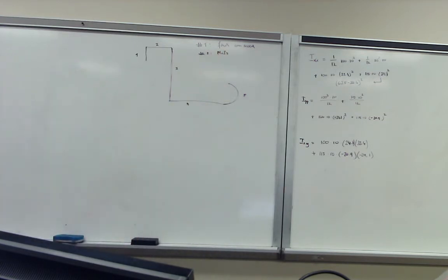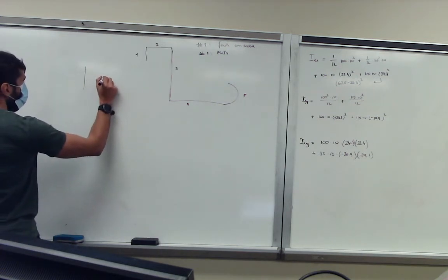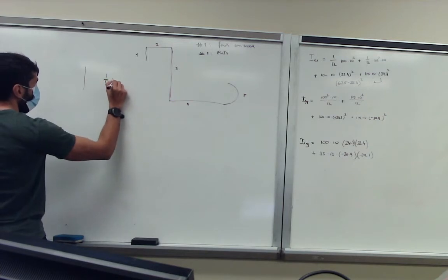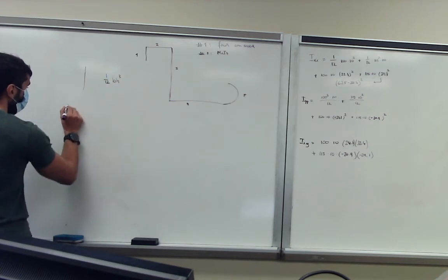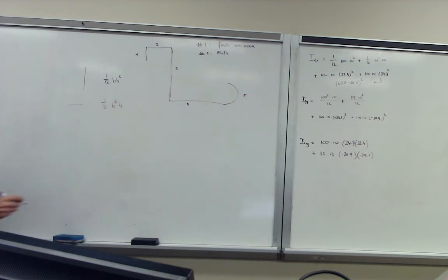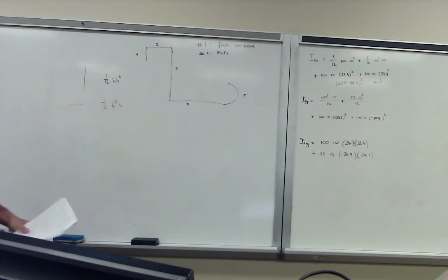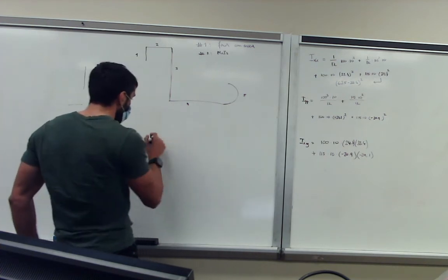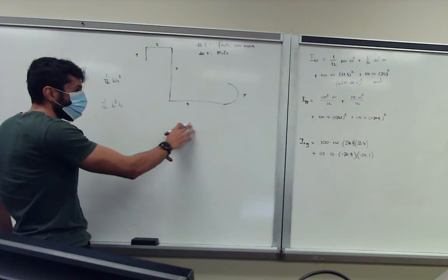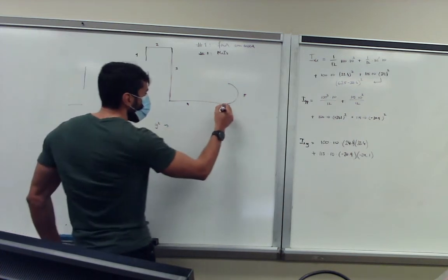You don't have to derive anything in this case, because we know by definition, the vertical flanges are given by 1/12 b h cubed. We know that the straights are given by 1/12 b cubed h, right? And we just fill in the corresponding distances. And if this is thin wall, then if it's a T, then it drops out. Now it becomes this one, right? What you can do is, yes, you can make a coordinate transformation. So your y distance, you go to